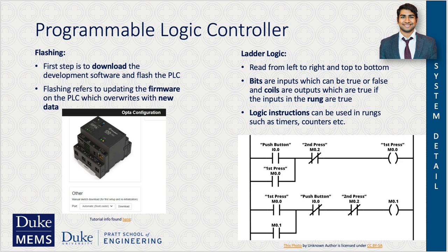So how do you program this PLC? Well, this PLC gives you a lot of flexibility, but I think in most industry standards, ladder logic is what's used to program most PLCs. So how do you read ladder logic? Well, it's read left to right and top to bottom, as can be seen here.